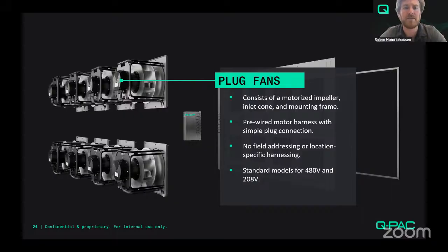They are all going to be from the major ECM manufacturers right now. So it's going to be Ziehl, Rosenberg, EBM-Papst, and if you really wanted to get into the details, you could choose which manufacturer. But in general, it's best to just think of it as a maintenance piece. The data and the performance of the product is really all about the multi-motor plenum fan. Another piece about what makes a multi-motor plenum fan is that you're going to have empirically derived performance for it as a whole multi-motor plenum fan, not just extrapolated out from each individual ECM. And that's something we're going to achieve with our airflow tunnel, but more on that later.